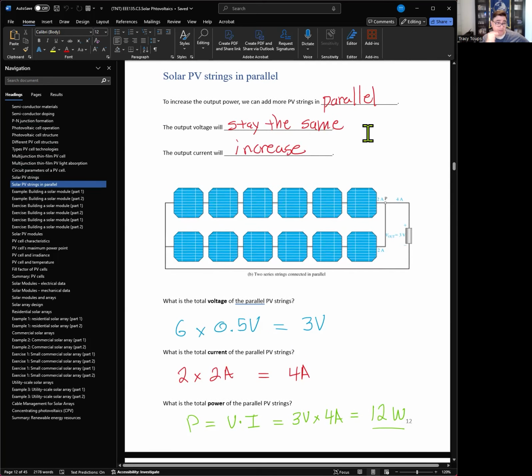So typically, design-wise, step number 1, ask yourself how many of them do you want in series to create a respectable voltage. One of the starting design process is always what voltage do I want my system to be? Do I want 12 volts, 24 volts, 36, 48? Okay. So let's say I want 12 volts, start putting them in series until you reach 12 volts. And then step 2 will be, well, how much current do we want?